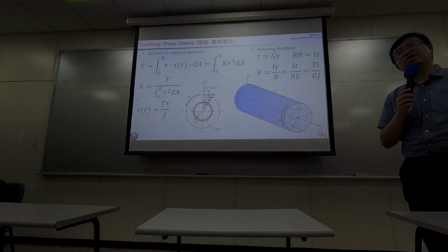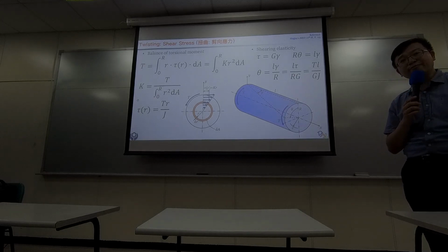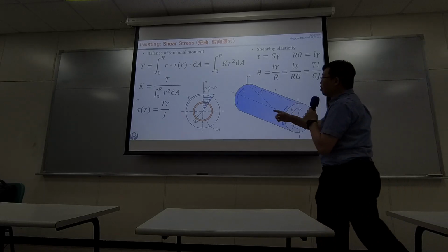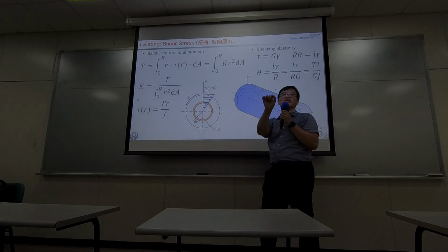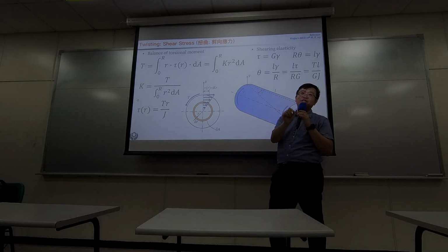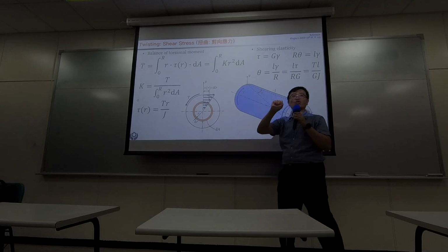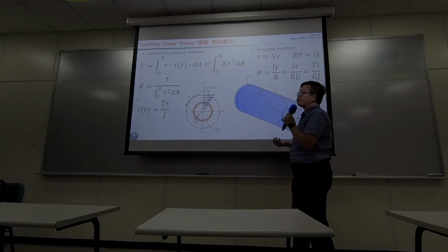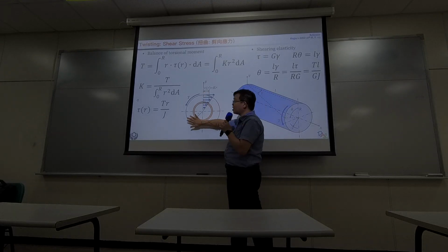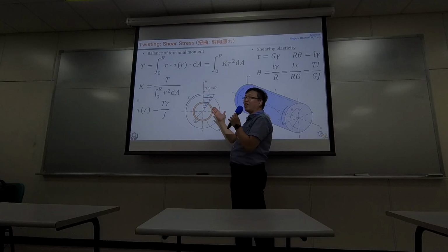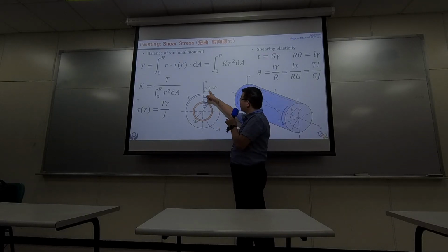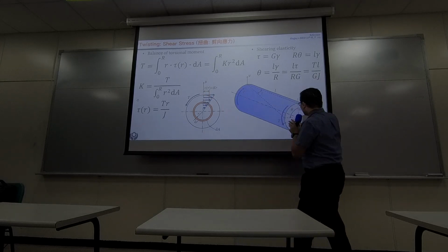So if there is the largest deformation, supposedly you should have the largest stress. But right at the middle, it's a point. Even after twisting, there's no deformation. It's still a point, same point. So right at the middle, there's no stress. That's why it's reasonable to assume the stress accumulated inside the cylinder is going to follow this kind of linear equation again.